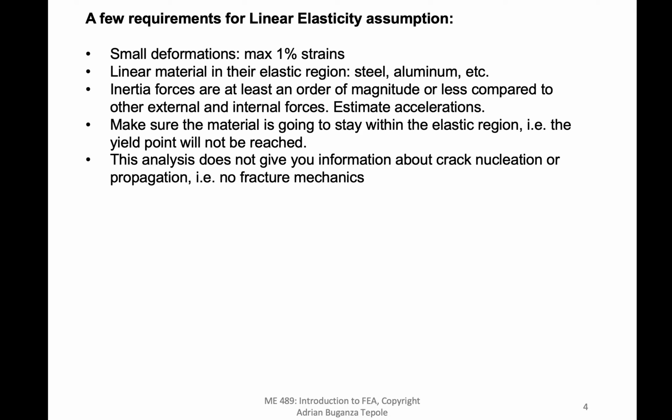So if you have strains that are bigger than that, then it's more likely that you won't be able to describe the problem with linear elasticity. At bigger and bigger strains, you start getting some nonlinear effects, both from the geometry and also probably the material properties. So make sure that your strains are small, and then you'll be fine. Then linear elasticity should describe the material.